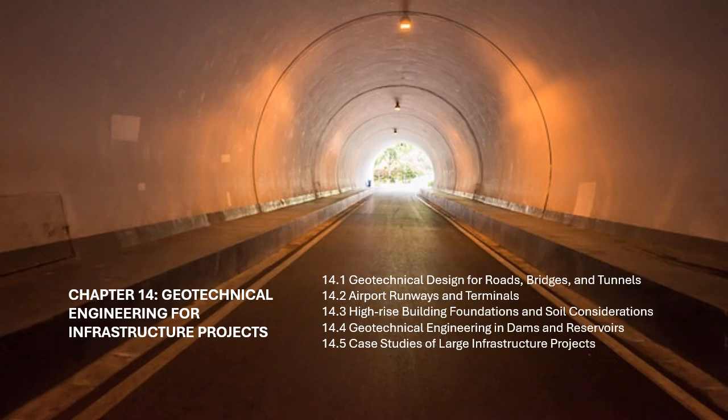Environmental and weather conditions. Airports are exposed to a wide range of environmental conditions, such as extreme temperatures, moisture fluctuations, and freezing. Geotechnical engineers must consider how these factors influence soil behavior, such as frost heave and soil shrinkage. They may use techniques like thermal insulation and frost-protected foundations to mitigate these effects.